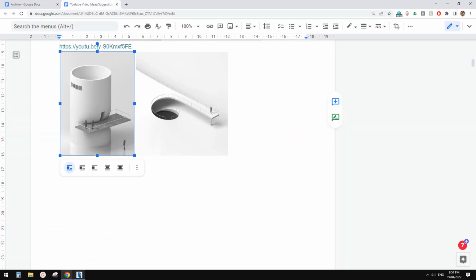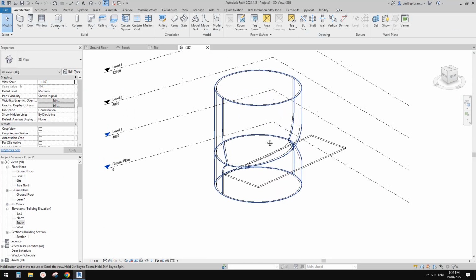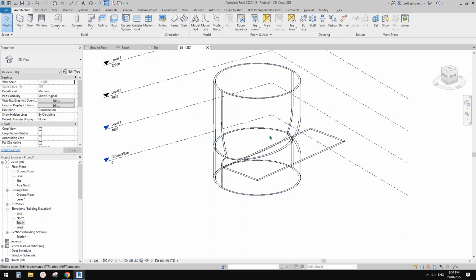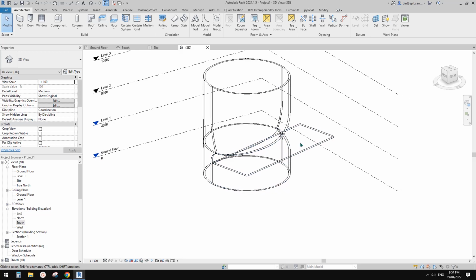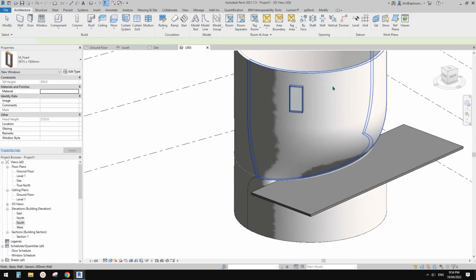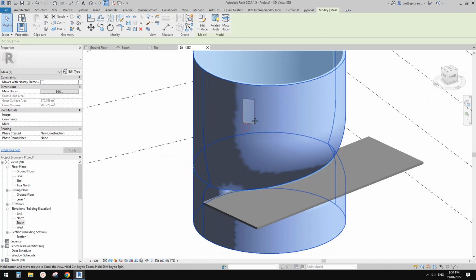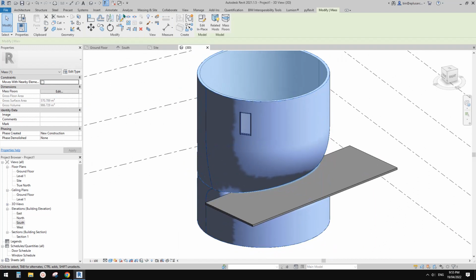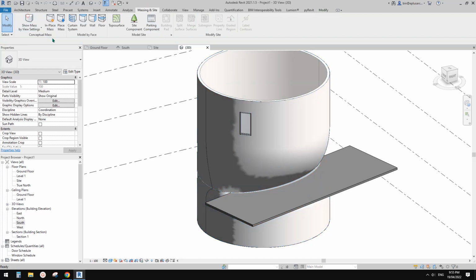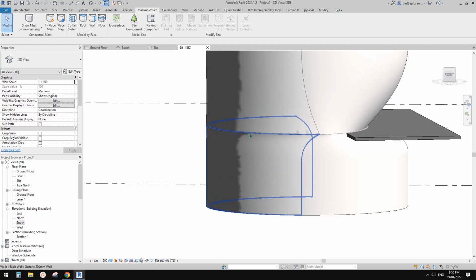it's quite close to that, right? And you can always place, because they are... Oh, what did I do? Sorry, I typed WF. I want to place a window, so that's WN. So go back to SD, WN, window. So you can always place a window on these walls because they are actual walls. Okay, and that's it. And also, of course, you can turn off the mask. So go there, uncheck that one. That's it. So not perfect, but